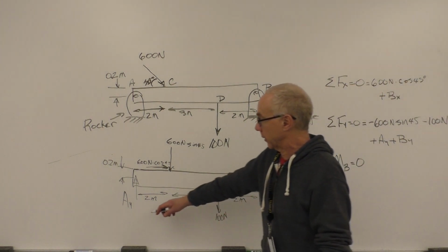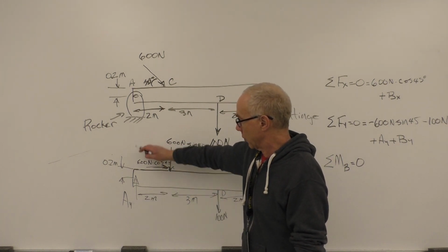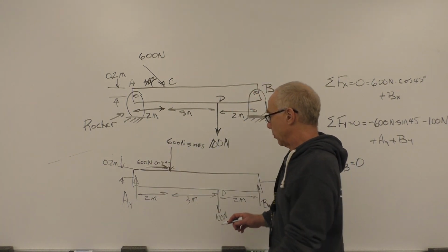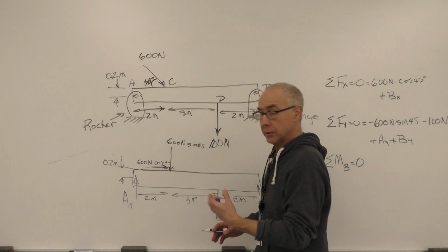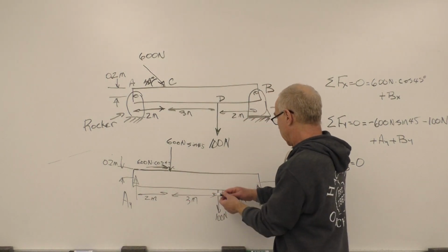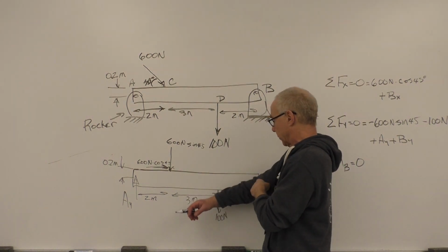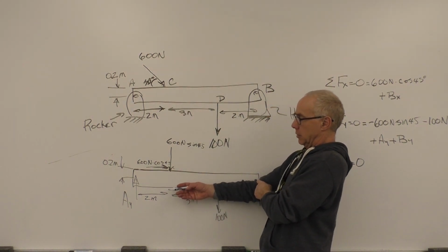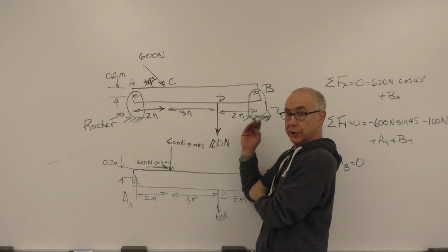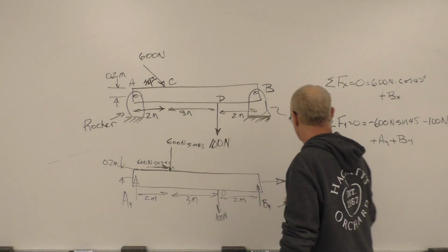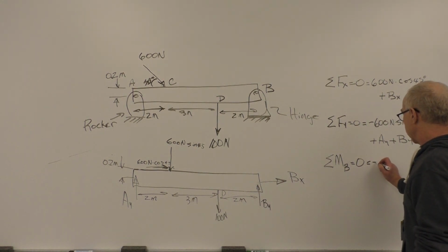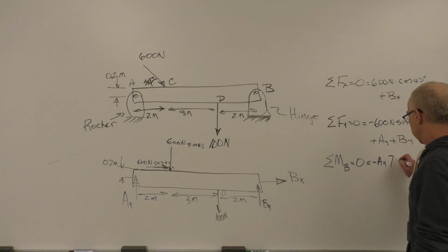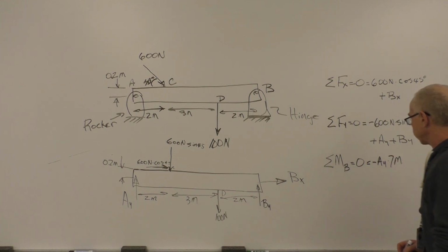So here we have, let's start here with AY. AY going vertical, and a moment arm in this case would be 2 plus 3 plus 2, 7 meters. And in this case, you can see that if we're rotating upward in this direction, that's essentially a clockwise rotation. So I'm going to put a negative value here. So it's going to be negative AY times 7 meters.